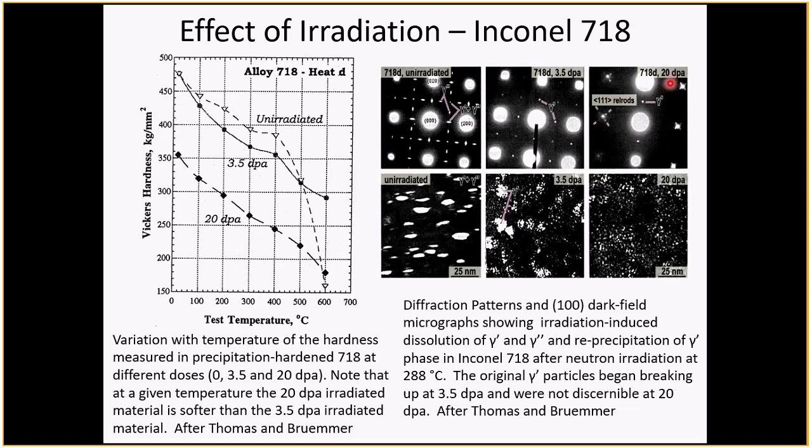And then you go to a further point, you get to a minimum. And this minimum may be this balance because the precipitates are being disordered. But thermally, you're also at, what temperature are we at? 288 degrees centigrade. The thermodynamics is also acting in the opposite direction to order the phase.